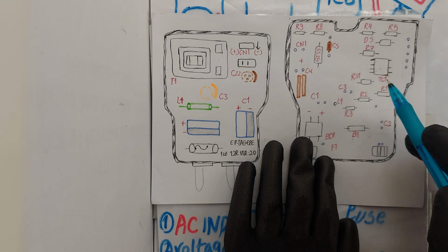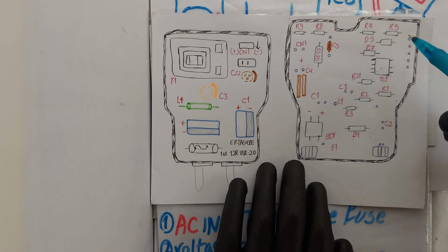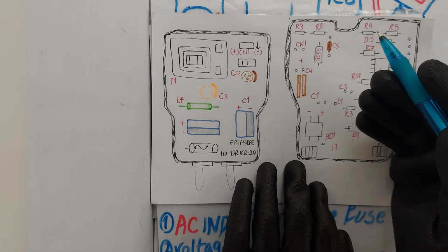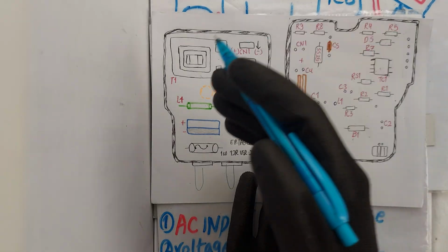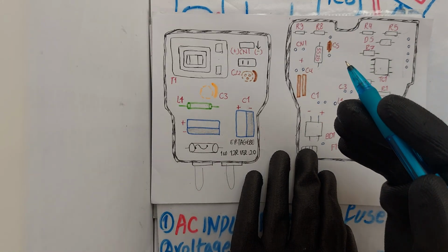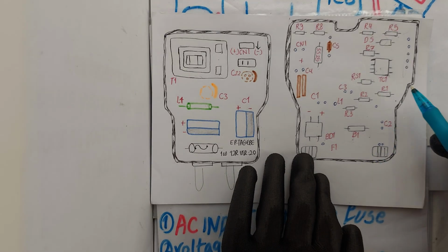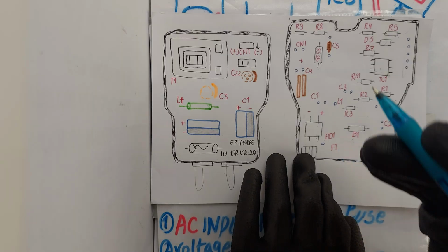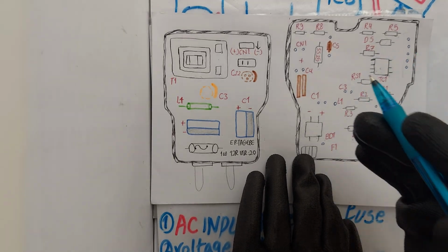This feedback is typically provided through a resistor divider circuit, R1 and R5, or an optocoupler, maintaining electrical isolation between the primary and secondary circuits. When the output voltage slightly rises or falls, this information is sent to the IC via the optocoupler. The IC then adjusts the internal switch on time to bring the output voltage back to 5 volt.